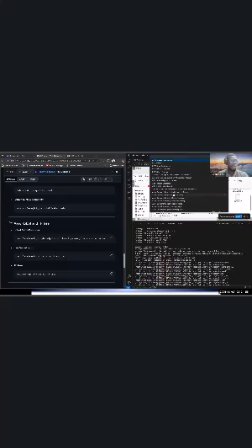So when you're running this on an actual ROS2 environment, with dual boot, a VirtualBox, a VMware Workstation Player Pro, or an actual Linux operating system, you install ROS the usual way. You might just have to create extra terminals via maybe the Terminator application. I think there's also an application on the desktop, so you just need to open a terminal. But for VS Code, you always use Ctrl Shift P and open terminal.